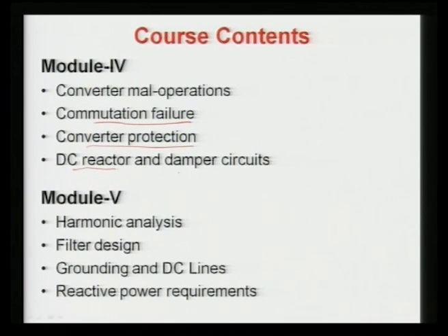Then in this module as well, the damper circuit, because we have various types of dampers. If there are voltage oscillations, then we have the anode dampers; if there are current oscillations, if you have line oscillation. So, various RC and RLC dampers are used, and they are discussed in detail in this module.